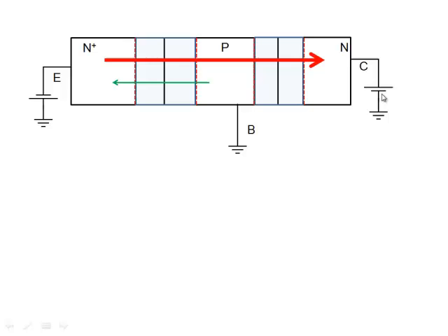Whether you apply 1 volt here, 2 volt here, 5 volt here, it doesn't really matter, because collection of electrons is easy. Electrons easily flow across the depletion region and reach the N side. So that's not an issue. The issue is how many electrons are there in the P region. That is what determines the current here. So whether I apply 2 volts or 5 volts or whatever, I will not find this current changing much, to first order approximation.